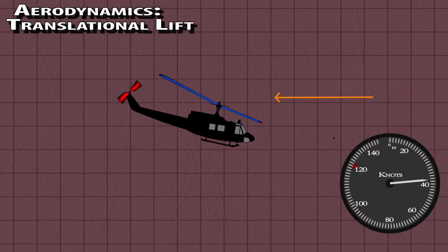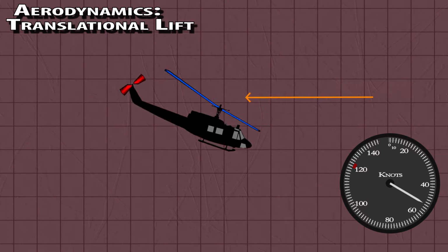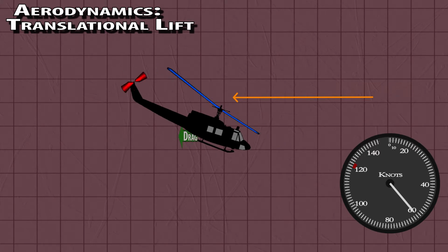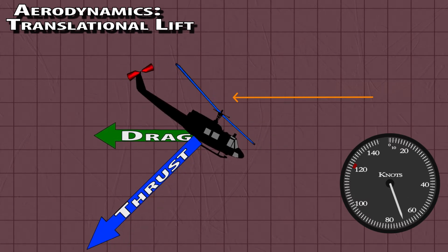We would have to tilt forward to either maintain hover in the wind or maintain forward airspeed. The more we tilt forward, the more the airflow actually matches and builds induced flow. At slow speeds, the tilt required is low and we benefit from translift more and more as we accelerate and tilt further. However, the faster we go, the drag on the airframe increases to the square of the speed. So more and more tilt is needed to move the thrust vector backwards to compensate. This means more air through the top of the disc and less performance.